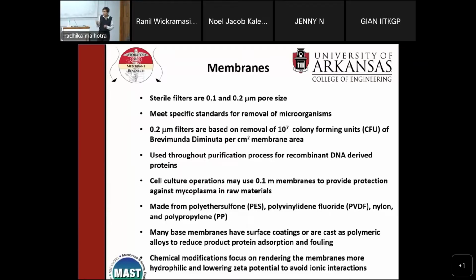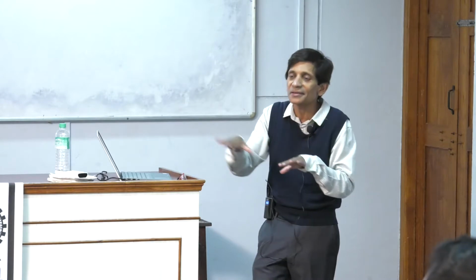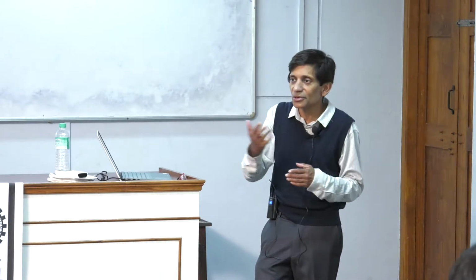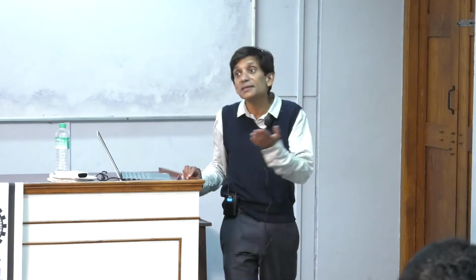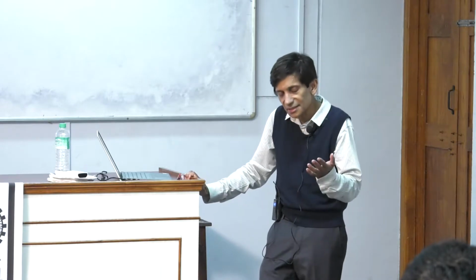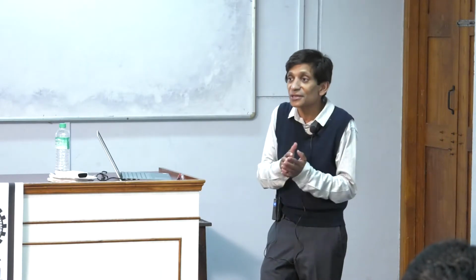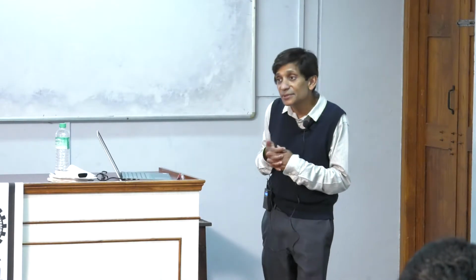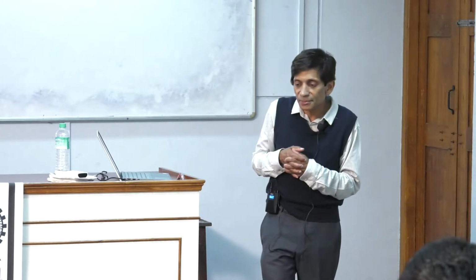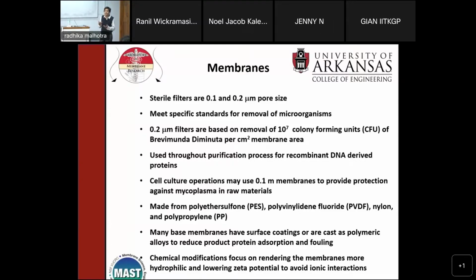For exactly the reason you said, because we don't know what the smallest pore size or the largest pore size is. We just know under these standard conditions, the manufacturer claims it rejects whatever the model bacteria is, and this is all standardized at a certain value. So it rejects these. But under your actual operating conditions, that may not be the case. This is particularly true, say, in ultrafiltration, where you talk about nominal molecular weight cutoffs, and you talk about 90% BSA rejection. Two membranes that are nominally, say, 100 kilodalton may perform very differently under actual operating conditions, okay? So one has to be careful.